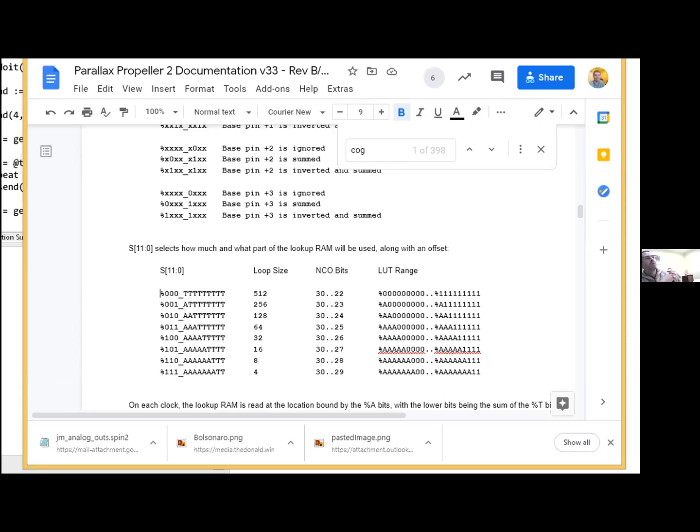No, the way it works is the only control a cog has is that he can say, do I want to receive writes from the other cog? So when the other cog is writing his LUT, you get those same writes. So it sets up kind of like a shared memory effectively. Not that they're physically shared, but if it's a two-way street, then whenever I write my LUT, I write yours also, and vice versa. So it turns our LUT memories into basically a shared RAM. Yeah, so you always read your own LUT. It's just when you're writing, you either write to your own only or to yours and your buddy.